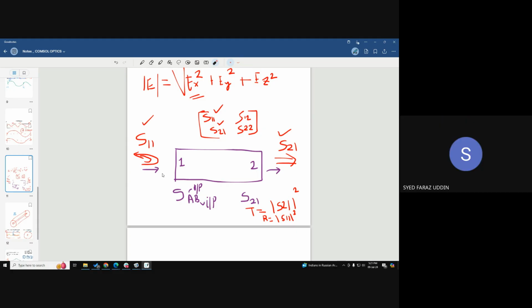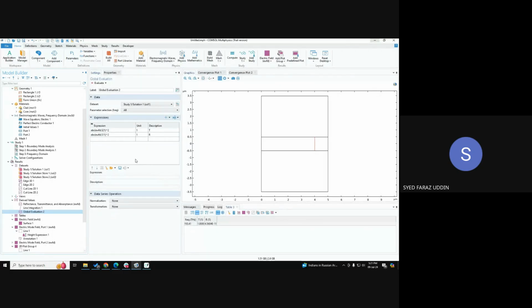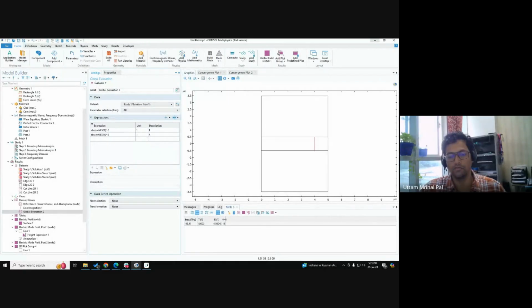When I click evaluate, I will get the values in the table at the bottom right. How can we interpret these values? If transmittance is one, it means full transmission. The maximum is one, so the value of T and R is between 0 and 1. Reflectance is almost 0, which means very little reflectance is coming out of it here.